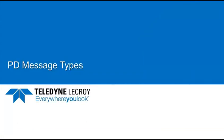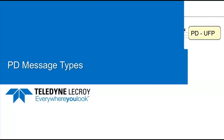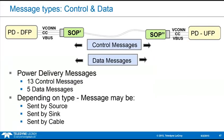Okay, I'll move quickly through the message types so we can look at some actual captures. So the CC pin allows us to detect the cable orientation. After that, CC becomes the main channel for negotiating and configuring all this added functionality, including power contracts, the alt mode stuff. Both link partners will send and receive packets over the CC line. There are 13 control messages and 5 data messages.